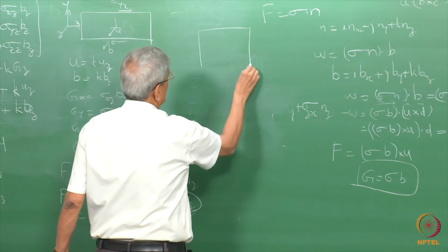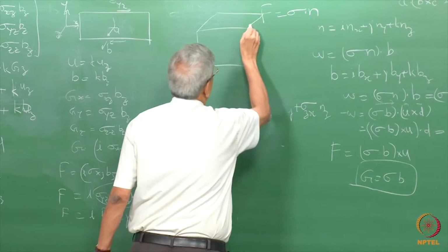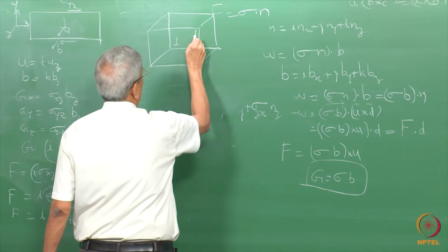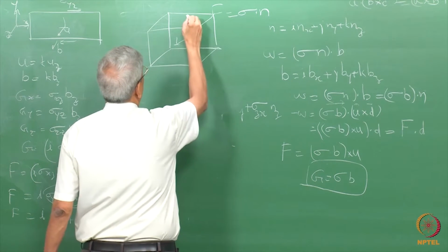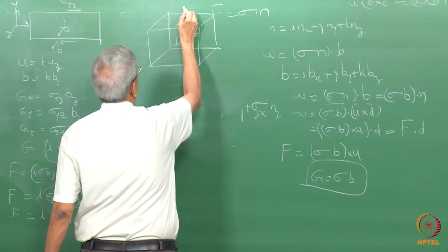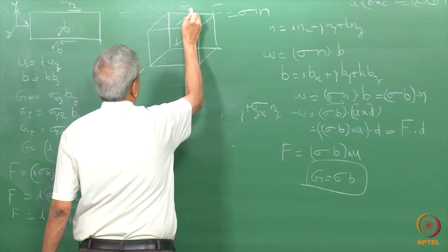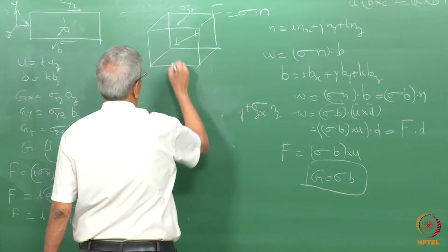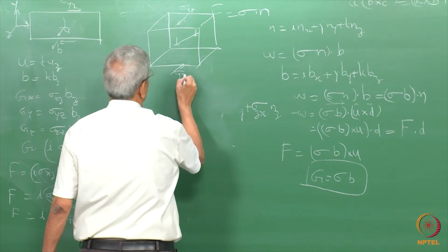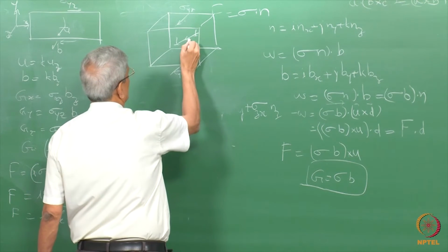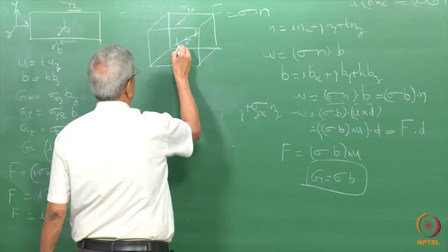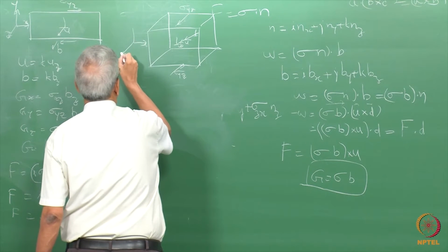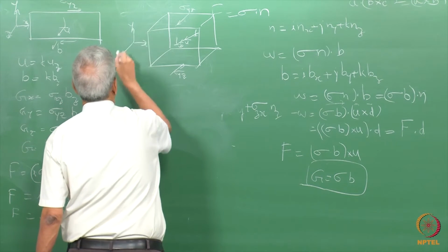In the case of a screw dislocation which we considered earlier, the stress is being applied yz in this direction and in this direction on the bottom surface, and u, the Burgers vector, is also in this direction, because this is the coordinate system which we have chosen, x, y and z.